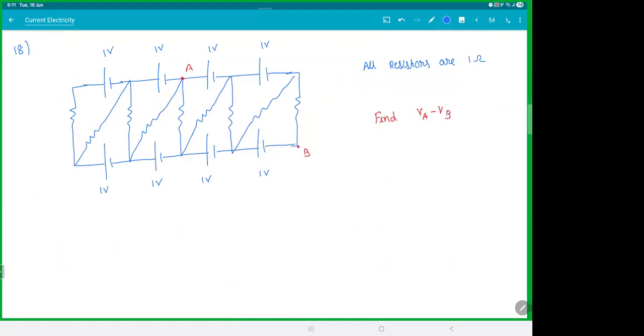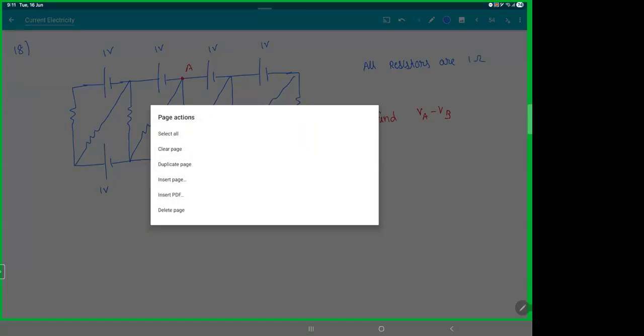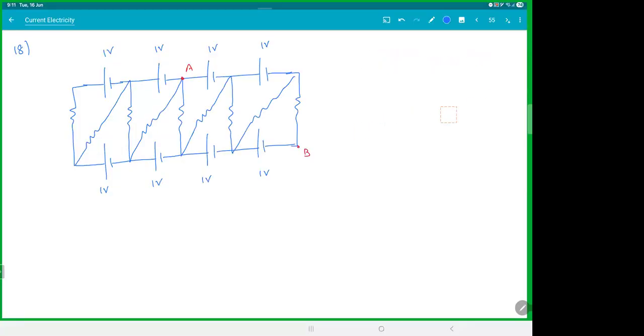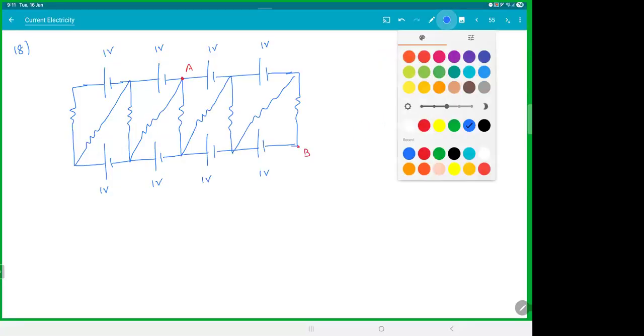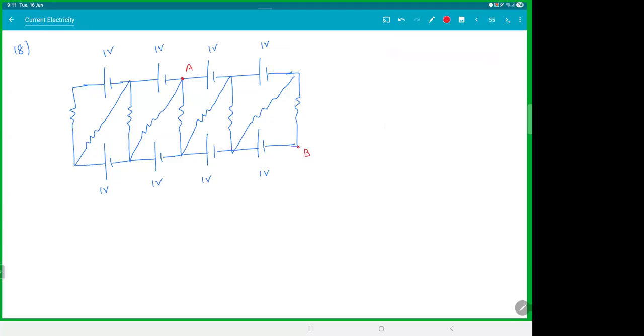Okay, this thing is a very interesting thing. Listen to this logic, what I said. If you try to do the individual, you will get it, but there are hell lot of variables. Listen to my idea here. Not only this circuit, you take any circuit, and if you cut it into two pieces, can I say the total current crossing this line in one direction must be zero?